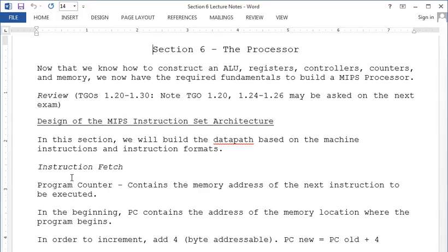Instruction fetch, I'm sorry, that should say that's 1.20. Instruction fetch. So I now have my 32-bit instruction. It's all binary values. So if I want to figure out what that means, what do I have to do to these? No, that's the 3rd stage. ALU is 3rd stage. So what's the 2nd stage? Instruction decode. I need to decode those values. What's the 3rd stage? ALU, right? So now I've decoded it. I've got the information from the registers. I actually put this value into the ALU and it performs some operation.